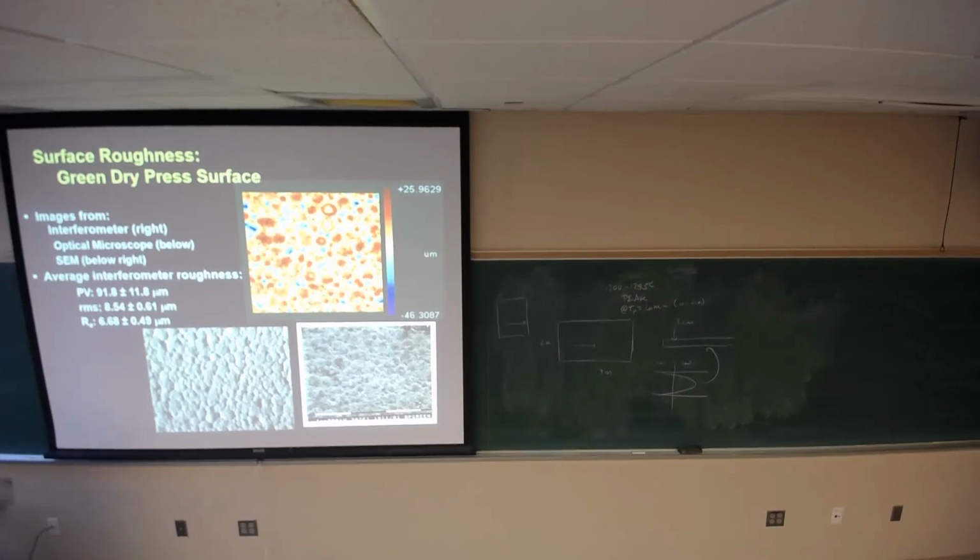And the evidence for this is when they take these large format tiles and start cutting them, they will often randomly crack. Now, there's no stress in the system other than cutting, and a crack will shoot on its own. You don't get the shattering that we get in glass, but we think you have a surface compressive layer. The water jet cutting is a pretty benign situation to begin with. So water jet is high pressure water with abrasive, and they'll cut, say, a sink opening in a large format tile, and then that crack will propagate. And so we think that this is a problem of cooling being too rapid. When cooling is rapid, you end up with stresses.